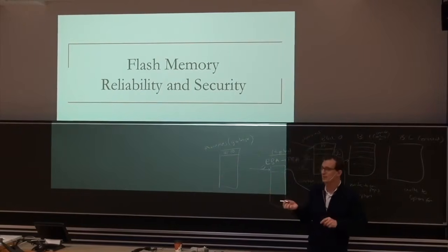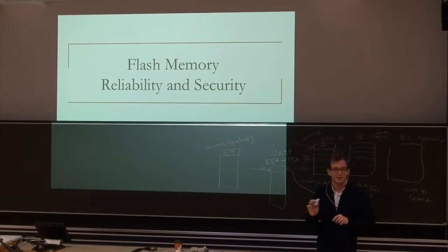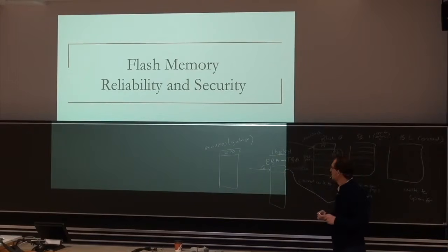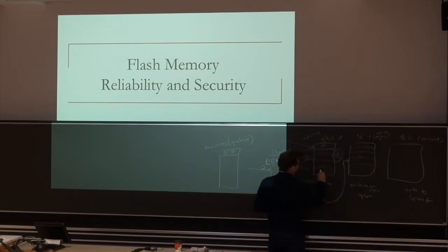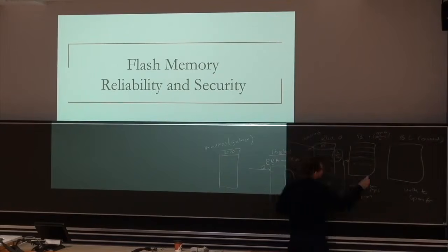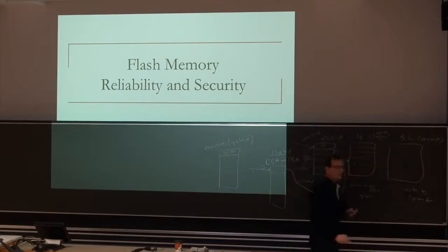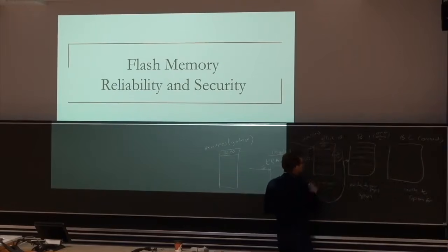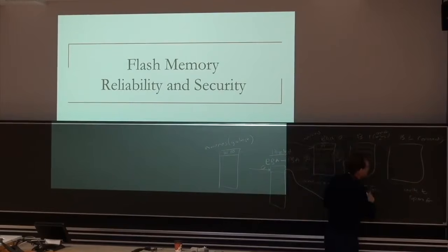A block, for example, you can only do 3,000 writes to a given block. 3,000 program and erases per page. Now, if some of the pages have over here 3,000, if some of them have 0 over here, that may not be good, right? Because you're not utilizing your entire drive. Some of them become unusable quickly, and some others become unusable, right?